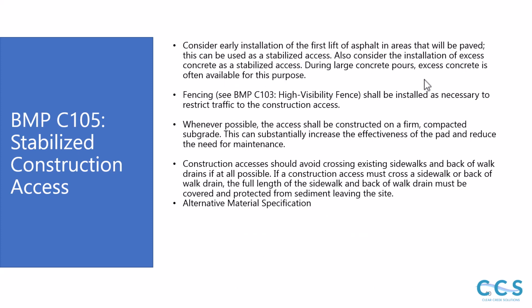So consider early installation of the first lift of asphalt in areas that will be paved. This can be used as a stabilized access. Also consider the installation of excess concrete as a stabilized access. During large concrete pours, excess concrete is often available for this purpose.